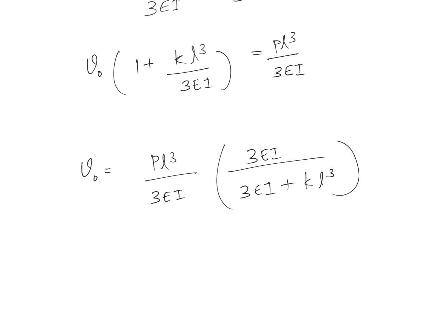That makes sense. So this kind of interpreting the answer will help you to eliminate a few options. I can simply say, had this expression been like this, I'm talking about the quantity in the bracket, sorry, there is an L cube, this expression is wrong, because I can definitely tell this answer is wrong. Why? Because as k increases, the displacement goes up, which is counterintuitive, because the stiffer the spring you have at that location, the less will be the displacement for a given P.